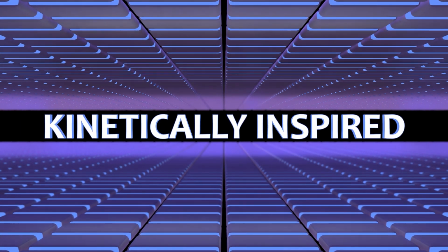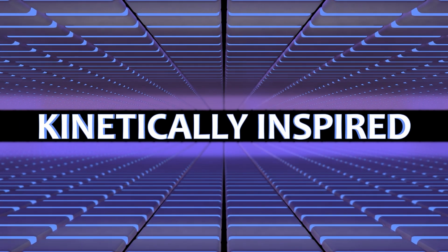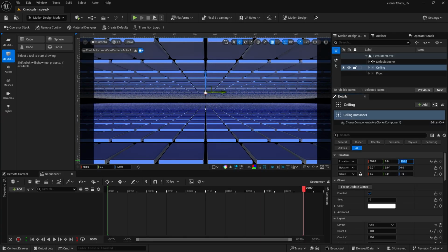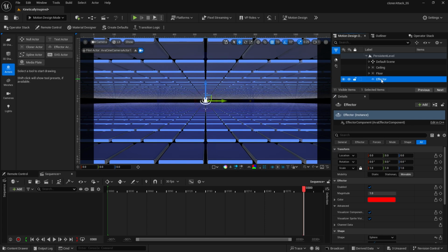To create the motion in the tiles, we're going to use an effector to affect the cloner. And we're going to need one for the top and the bottom for each of these. We'll set up the first 2, and then we should be able to duplicate the others. So back in our project, I'm going to go to actors here, and then I'm going to add in an effector actor. So for this effector 1, I'm going to go ahead and label that. With it selected, we'll drop down into the properties and take a look at this.